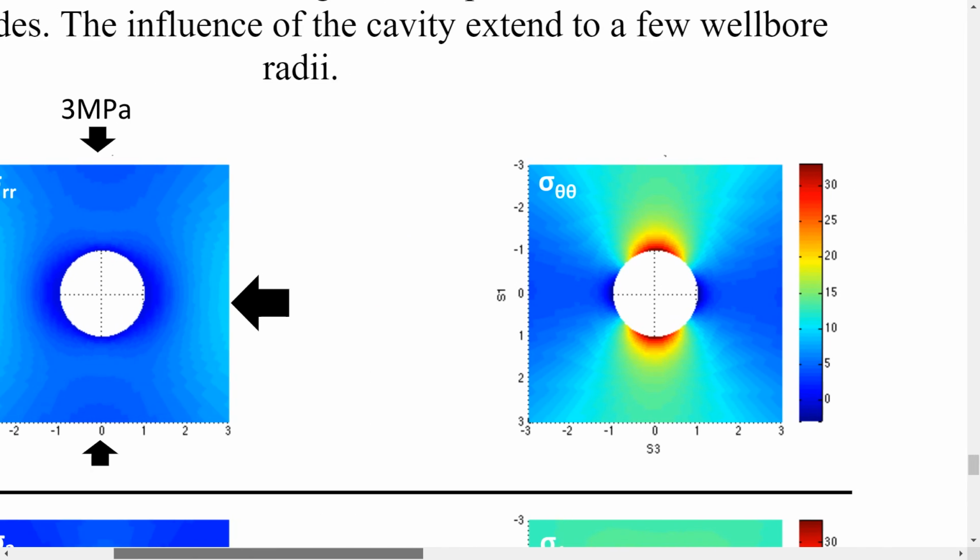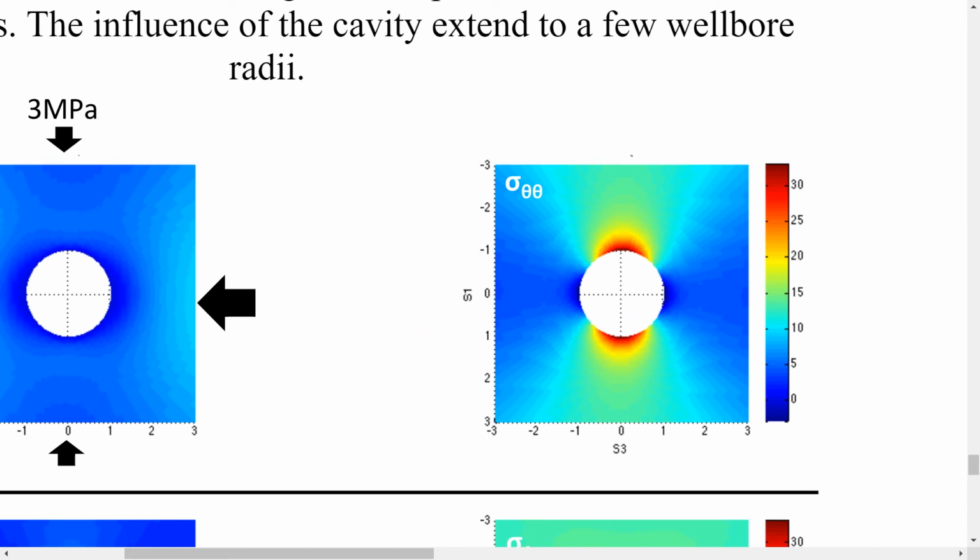And we're going to see that later on, because this is very useful. Sometimes you can see a wellbore and say, well, the shear failure is located, say, at 45 degrees from the north towards the east. And because of the orientation of that failure, you can say the stresses probably are coming in this direction, because the wellbore is telling you that. The wellbore reveals the direction of the stresses if you have failure in them.